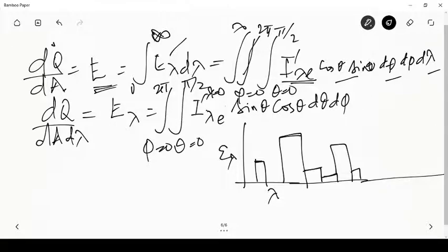So this can be written as epsilon lambda E lambda b. Okay, and that epsilon lambda being constant in those regions, you can use the fractions that we defined yesterday, f of 0 to lambda t. Those fractions can be used for this wavelength interval, and then this interval, and this interval, and we can use the delta f values and calculate the expression.